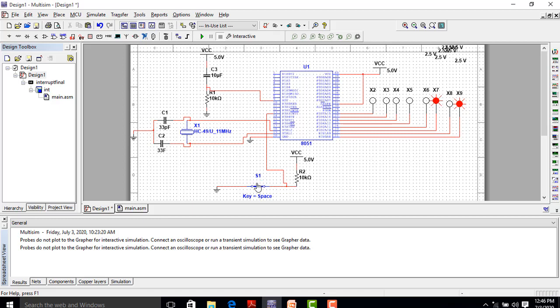So what should happen? In the beginning these all should be 0, and when I press this the first time, okay, the negative edge is triggered, it should become 1. When I press it again, I open it, and when I press it again, because I want a negative edge, an edge will occur when I move from this position to this position, remember, right? So when I press the first time, I should get 1. When I press the second time, I should get 2, and correspondingly.